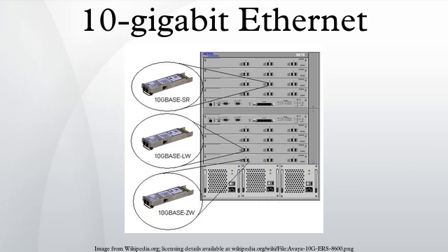10GBASE-LX4. 10GBASE-LX4 is a port type for multimode fiber and single-mode fiber. It uses 4 separate laser sources operating at 3.125 Gbits and coarse WDM with 4 unique wavelengths around 1310 nm. Its physical coding sublayer 8B10B PCS is defined in IEEE 802.3 Clause 48 and its physical medium-dependent PMD in Clause 53. It allows a range of 300 meters over FDDI grade, OM1, OM2 and OM3 multimode cabling.